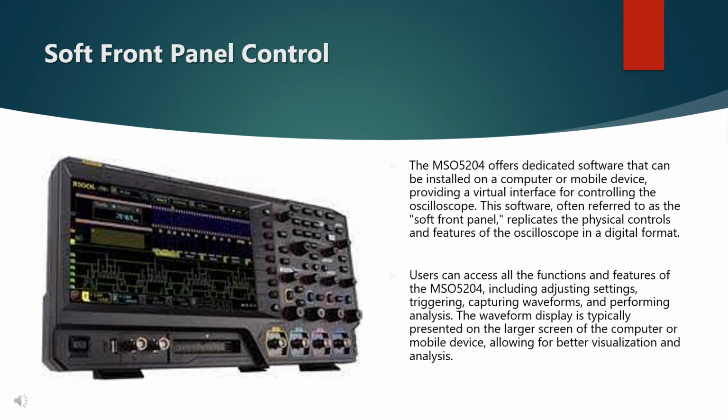The waveform display is typically presented on the larger screen of the computer or mobile device, allowing for better visualization and analysis. To utilize soft front panel control, users can connect their computer or mobile device to the MSO5204 using a USB or Ethernet connection. Once the connection is established, they can launch the soft front panel software and establish communication with the oscilloscope.